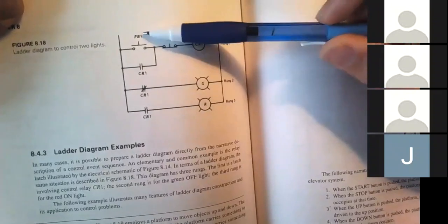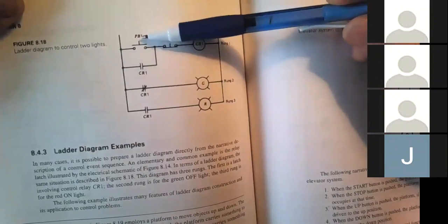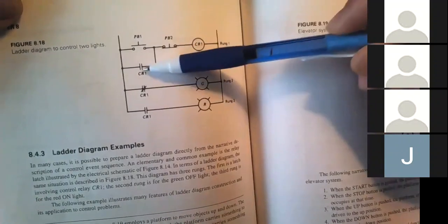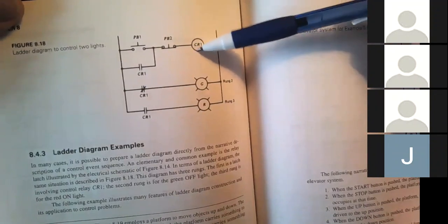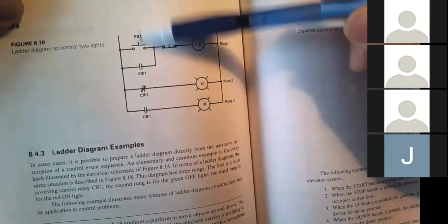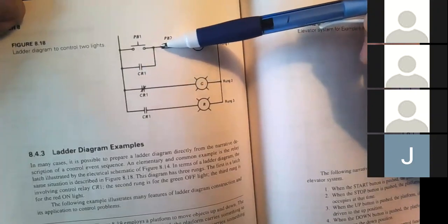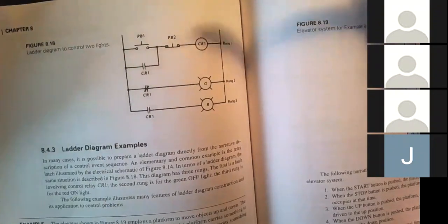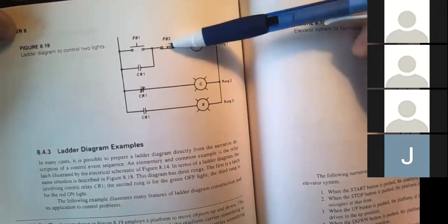So this is one way to use a relay in the discrete control system: a start and stop. When we push the start button, it will automatically latch. This contact will close, latch on, and energize the coil. When the button is released, this parallel latching branch keeps the circuit closed and the coil energized, so the motor will remain started until we push the stop button.